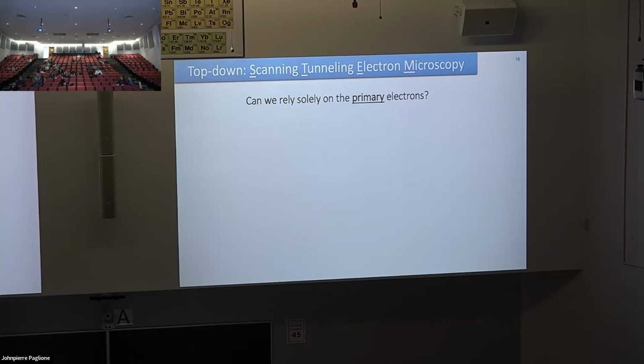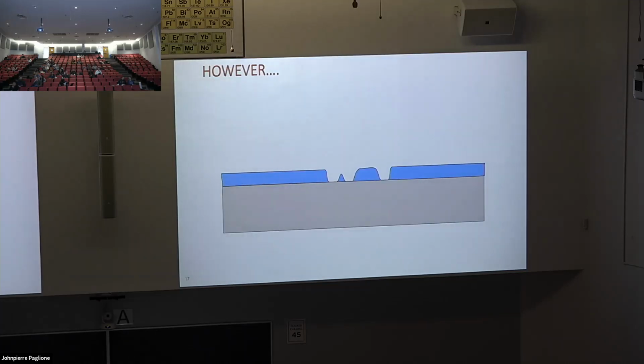The nice thing is that in this picture, you can imagine that you have this resist, and then there's a layer of graphene sitting in between. If you use some etchants like oxygen, that will etch your graphene, but it doesn't etch the silicon oxide. Okay. So you can change the chemistry that you're using to etch, making it more selective towards one or the other. But if that's the case, you don't have the HBN layer between the graphene and the silicon oxide, right? But I saw slides, you do have the HBN as a spacer.